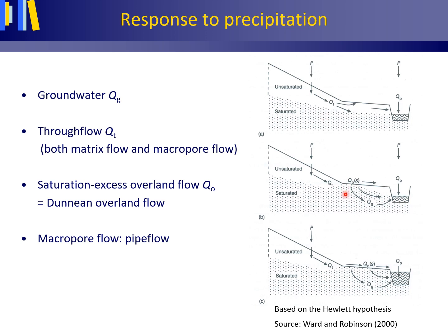Figure B shows that convergence and infiltration in the lower slope areas leads to surface saturation and groundwater recharge, which will create both an overland flow and a groundwater flow contribution to the stream, with the groundwater ridge expanding in some locations into a wider area of surface saturation as shown in figure C.